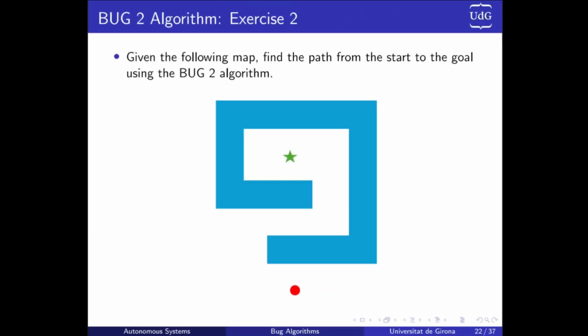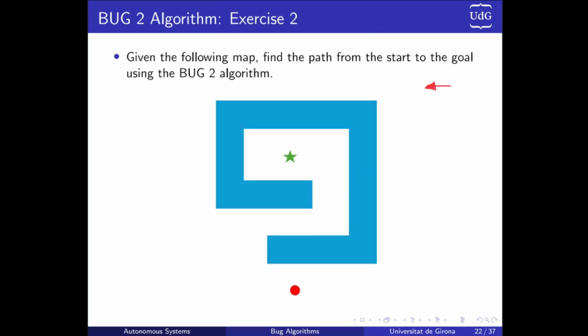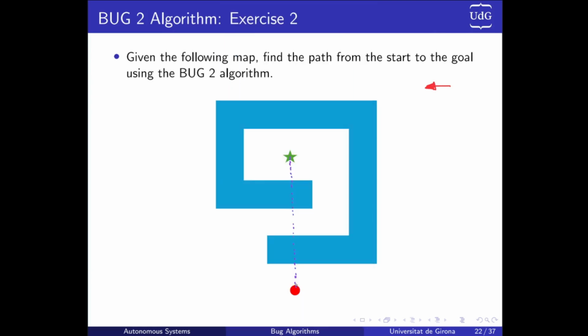Let's see what happens here. That is when problems happen. Okay? Previously we had problems moving left. Okay? With the Bug Zero, problems moving left. Let's see now what happens. Let's draw the M line. Okay, this is the line. And now let's follow left. We move here, okay, we need to follow left.